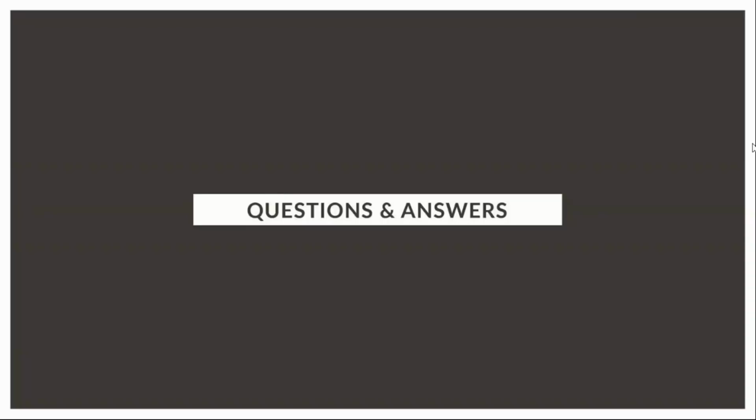Next question is by Marco. He wants to know, can you make a kind of skirt effect with two lateral vortices in the underbody of the car? If it's possible, why does it physically work? Let's say there have been times in F1 where people were using this principle with, for instance, exhaust blowing. The exhausts were blown on some surfaces that were creating a vortex, and they were sealing the side of the diffuser.